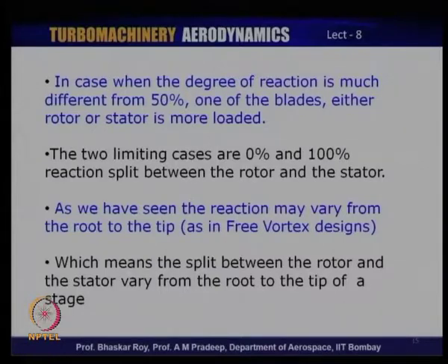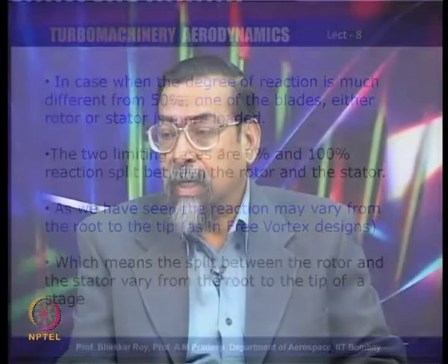That means, the loading pattern would vary from the root to the tip of the blade of a rotor, and the loading pattern on the stator would vary in the opposite manner from the root to the tip of the blade. Now, this is what exactly a free vortex or a near free vortex design would essentially yield. So, this variation from the root to the tip of free vortex kind of design is an important issue. We have to keep that in mind, unless you are going for a constant reaction blading.